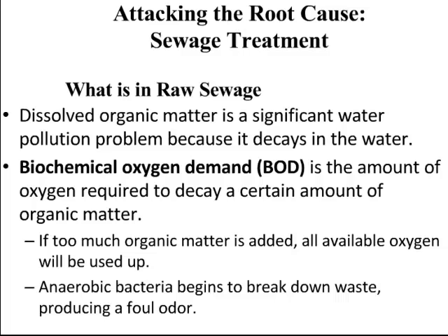So BOD is the amount of oxygen required to decay a certain amount of organic matter. It's how much oxygen is used up by that water as the bacteria grow in it because of the waste that's in the water. If we add too much organic matter, feces or urine, to a water body, then the bacteria grow too fast and they use all the oxygen up.